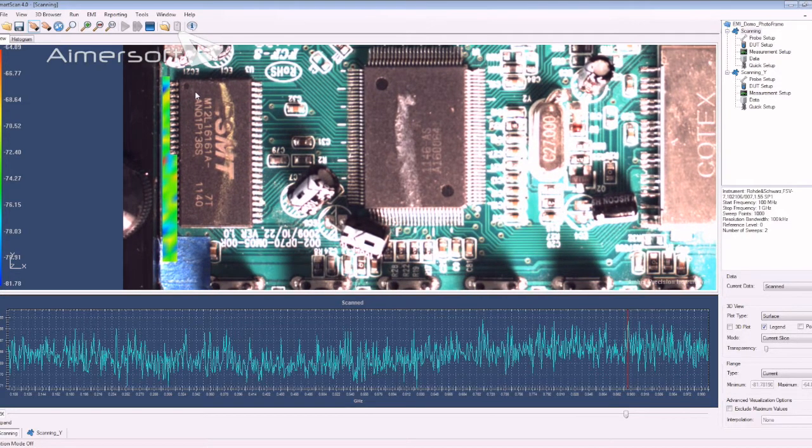If we find a peak, we're going to see it immediately on the bottom plot. This bottom plot, this maximum curve, is a really convenient way to understand what's going on on the board just by looking at one single plot. We can clearly say that, for example, at this frequency, somewhere on that DUT we definitely have a very high rate of radiation, and at some frequency, if there are no peaks, we can say that at that frequency the board is quiet.